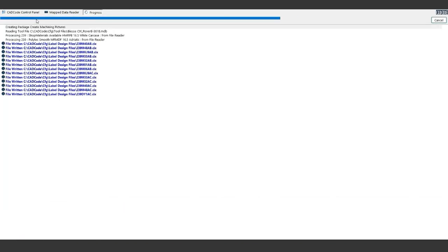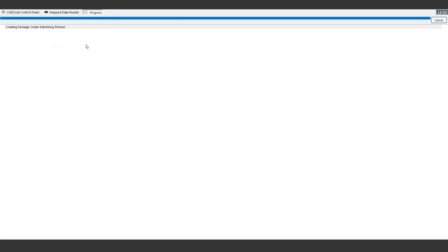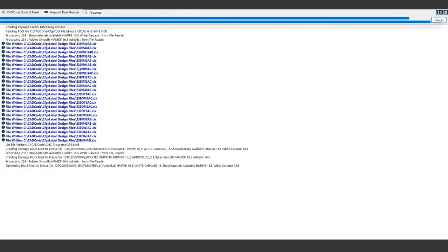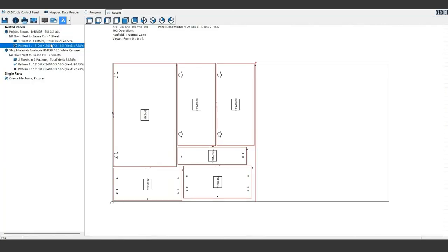So my demo system here is set up for a BSE CNC, which is why I'm producing CIXs. Looking at the color board here, we've just got those couple of doors and drawers that we've built, but we also got this additional route that we've included to salvage as much of this board as possible. So therefore we get the best offcut possible from that nest.